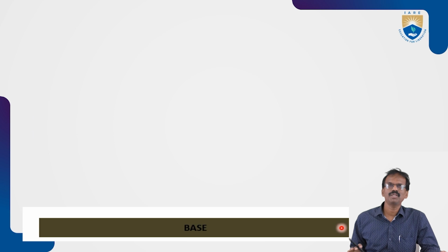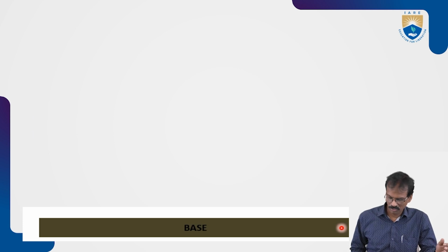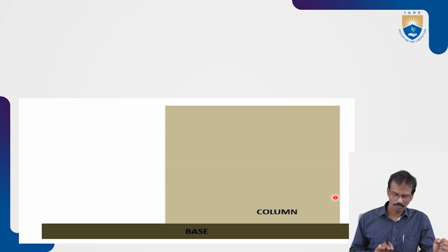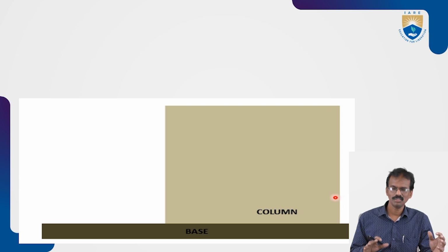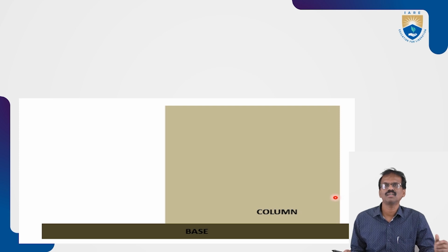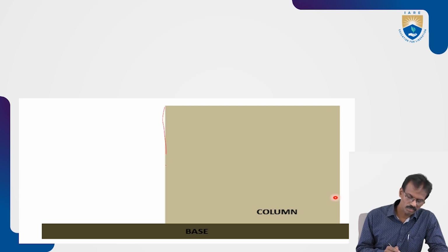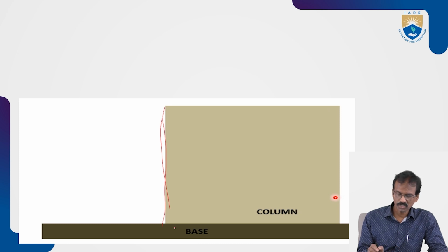You know that the bed base is made up of cast iron by the casting process. Cast iron is a very hard and brittle material that can withstand all types of vibrations. On this base there is a column, a rectangular hollow type column. Inside the column there are mechanisms used for conversion of rotary motion to reciprocating motion, and some lubricating systems are also provided in the hollow space. In the front portion there are some guideways, and the top portion also has guideways, on which the ram will move. In the front portion the table will move in upward and downward direction.